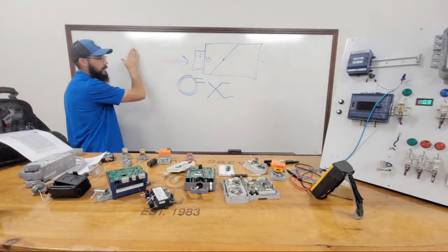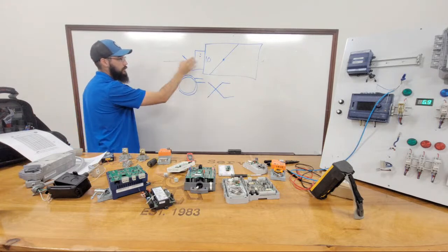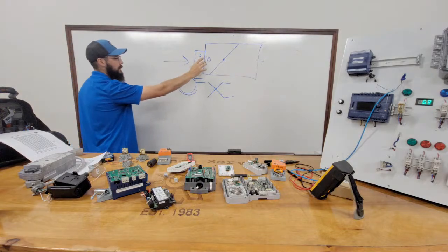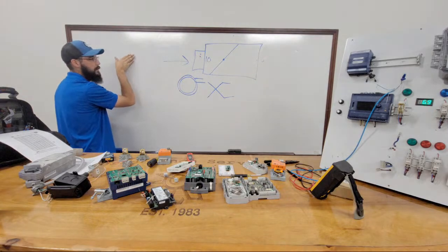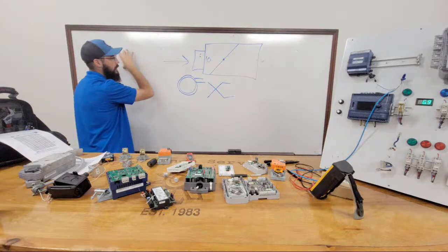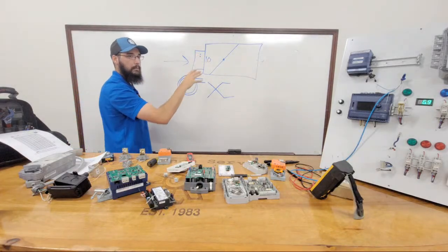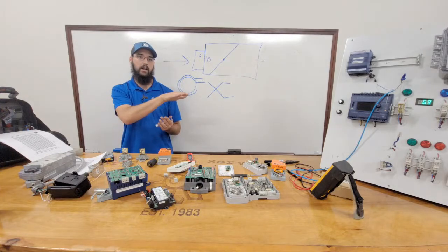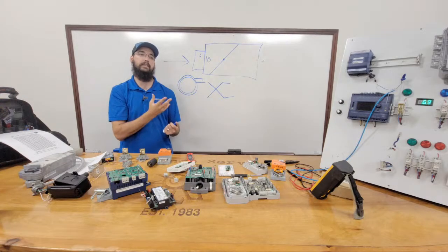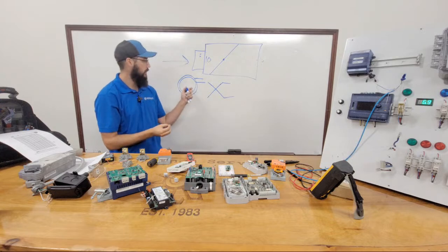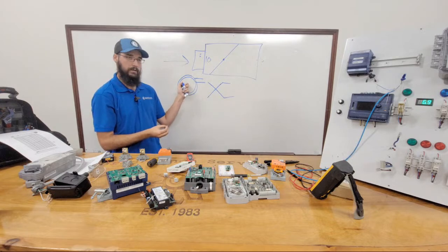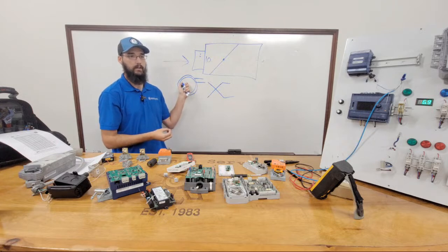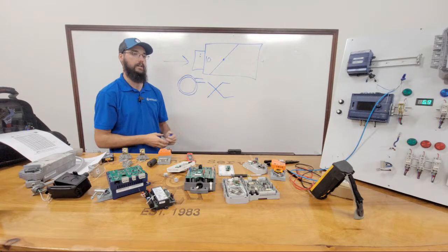The point of the hard pipe is, if you use the ratio properly, again, I'm sorry, I'm not remembering it off the top of my head, but if you use that ratio, it's enough length of hard pipe that it allows that airstream to stabilize and all that turbulence to be taken out of it enough that those can pick up properly. And that's the whole point as to why we need to do it that way, so that we can read our CFM.